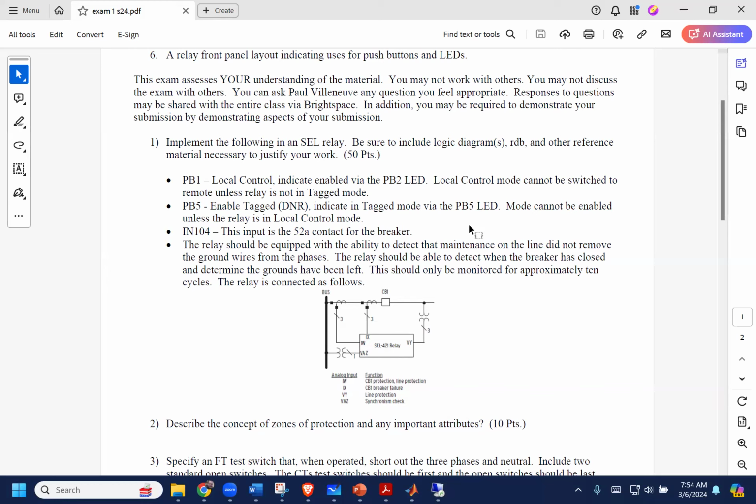One of the things that companies do is if they have a transmission line that they've done some work on, they sometimes will ground each end of the line to make sure that if some odd circumstance where something closes in, then the staff that are working on the line are protected because they can see that the line is grounded. So the voltage won't go unexpectedly high. It'll actually be detected by a relay and actually cause a trip. So it provides a level of protection where you would hang these ground wires.